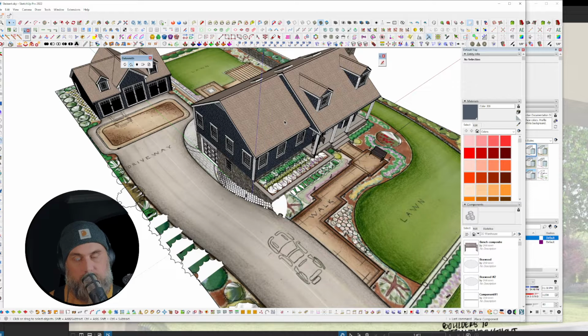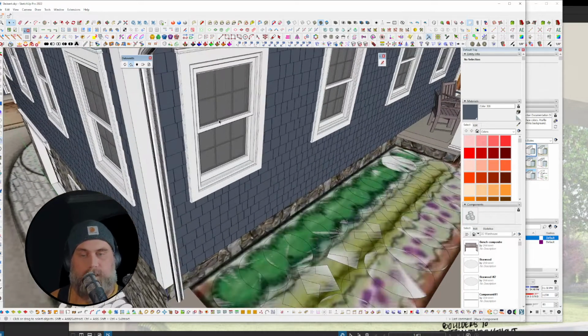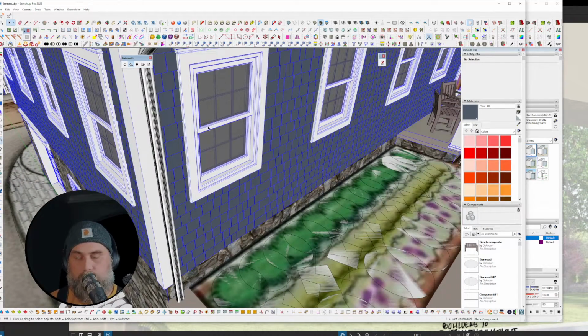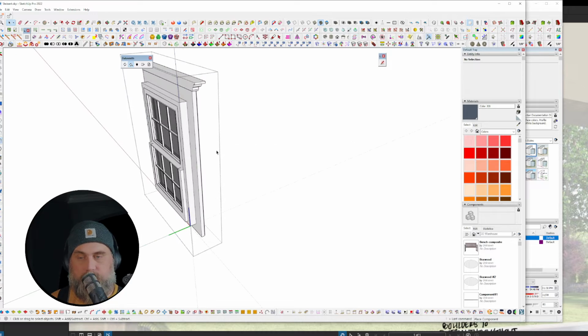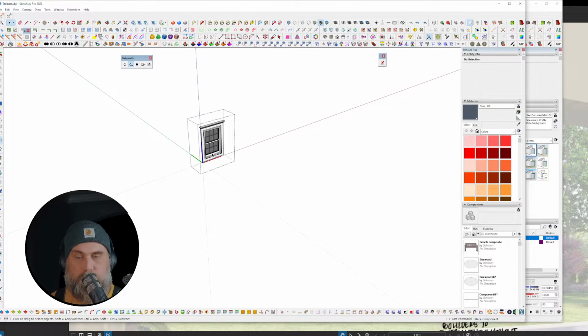For your house model, you want to collapse that by material, right? Because you're getting in there, you're adjusting the materials, you're setting some reflectivity, some bump mapping. So you don't need to have every little piece of a window, let's say. You don't need all of these interior pieces. You don't need all of this to be separate, every window pane to come in and be accessible. There's no reason for that.